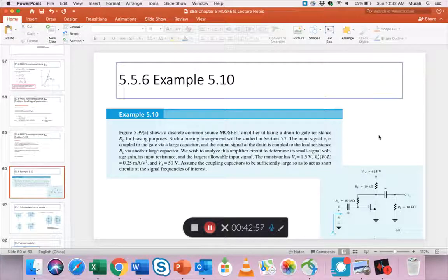These are coupling capacitors, and basically all we do is ignore them when we do our circuit analysis, because it's assumed that the coupling capacitors block DC when they have to, when we are doing small signal analysis, and they are only relevant. They kind of behave as short circuits when we are doing small signal analysis, is the point. So you might as well just totally get them out of your mind right away.